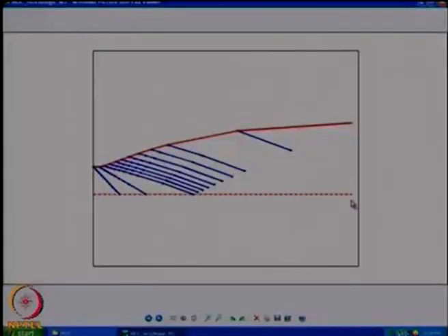I have designed a nozzle for Mach 3 here for gamma equal to 1.4. You can see that this is a throat section, this is your A star location ideally, and I have created number of points on this to be 10, initial points on my initial line to be 10. How did I get these points?